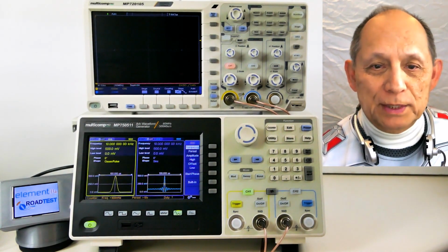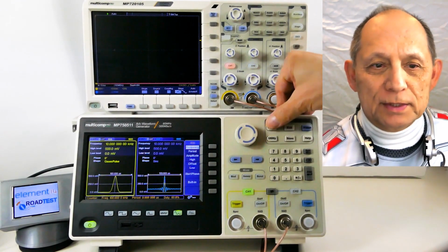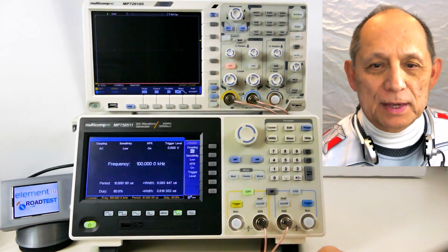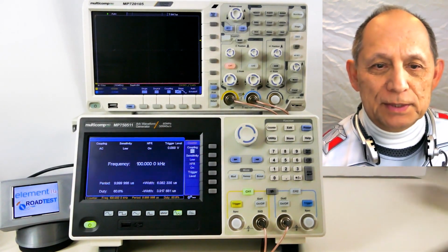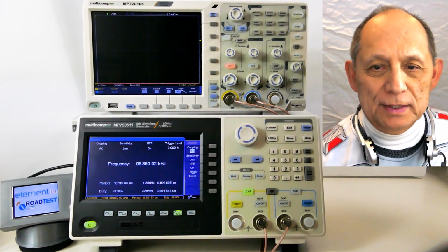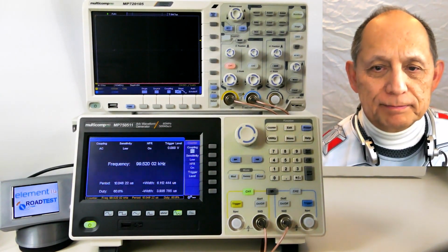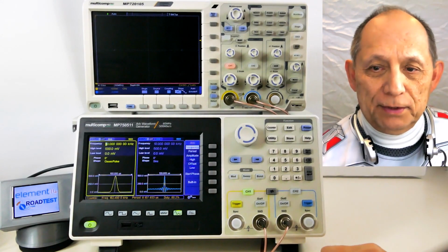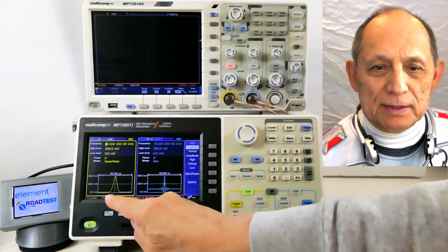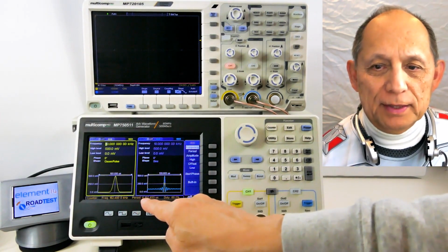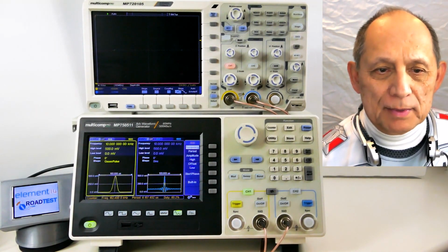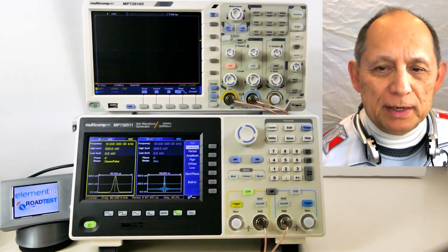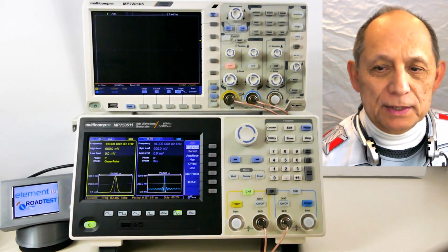It isn't just a waveform generator either. It also includes a 7-digit frequency counter, with a separate BNC input on the back. I will adjust the frequency a bit just to see it change. When generating waveforms, the separate external input frequency, the period, and the duty cycle are all displayed continuously at the bottom of the screen. I'm going to run through some applications of waveform generators and then show some neat things that this particular generator can do.